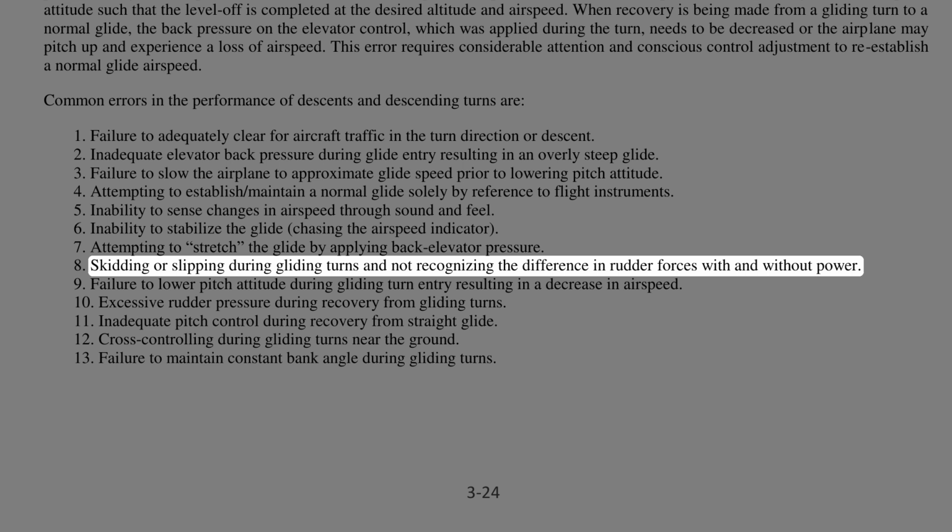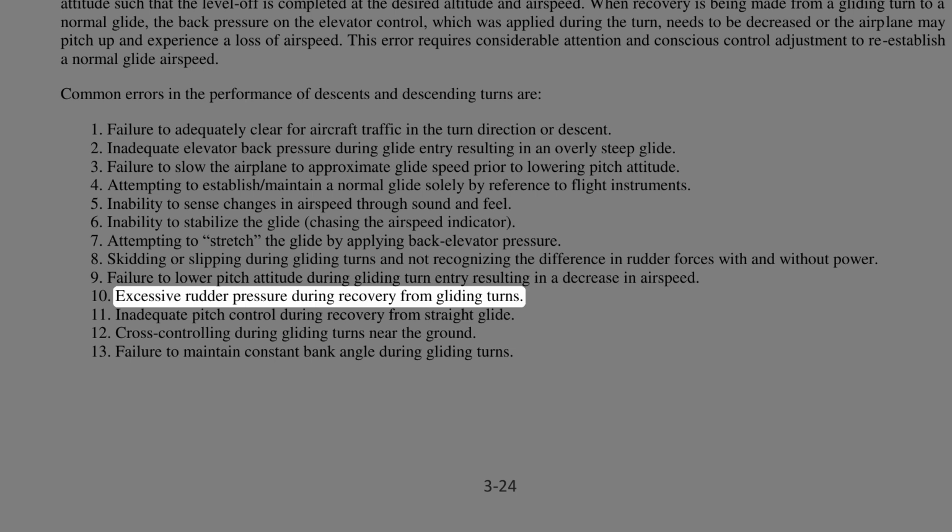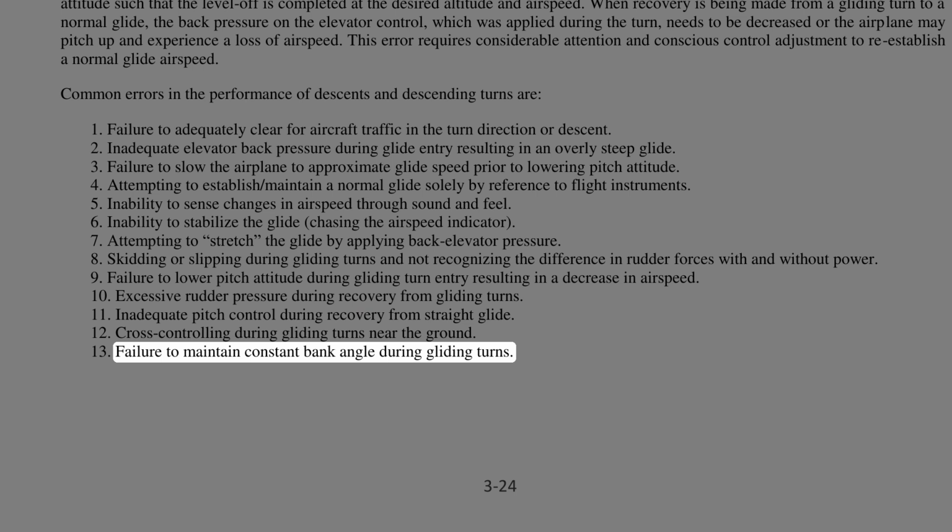skidding or slipping during gliding turns and not recognizing the difference in rudder forces with and without power, failure to lower pitch attitude during gliding turn entry resulting in a decrease in airspeed, excessive rudder pressure during recovery from gliding turns, inadequate pitch control during recovery from straight glide, cross-controlling during gliding turns near the ground, failure to maintain constant bank angle during gliding turns.